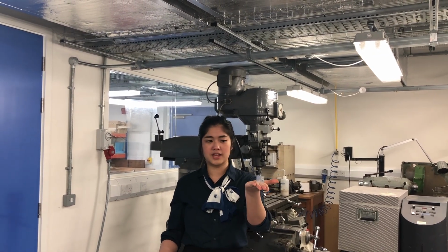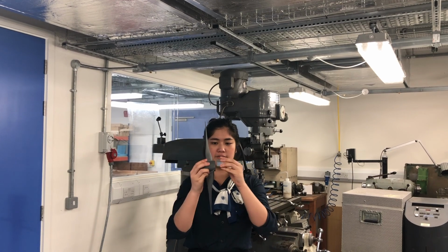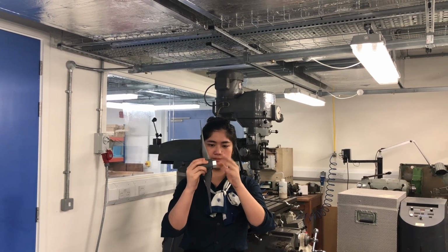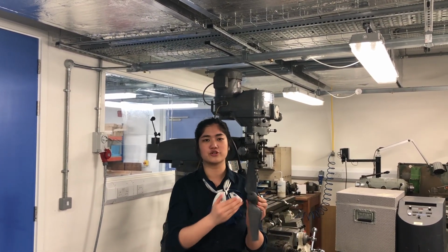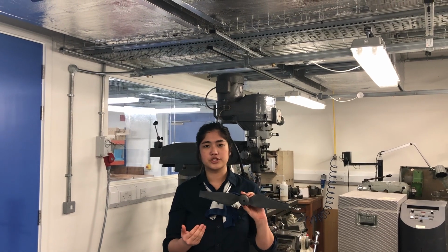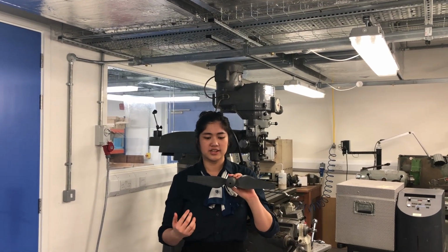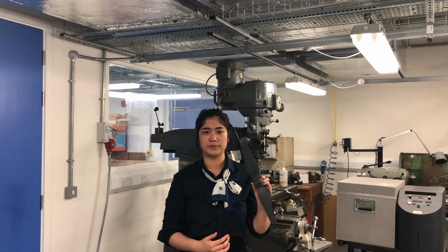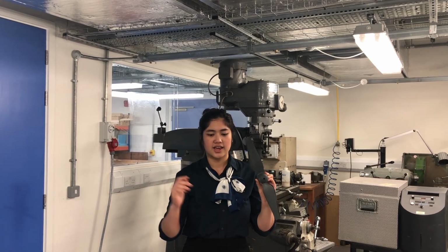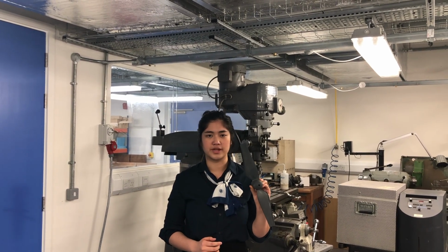First, draw up the hub. Design the turbine around the specifications of the hub. Tighten and adjust the size of your nose cone as needed. Make sure the wind turbine has been designed to rotate clockwise when viewed from the direction of the wind. It also should have a TSR of between 3 and 8.